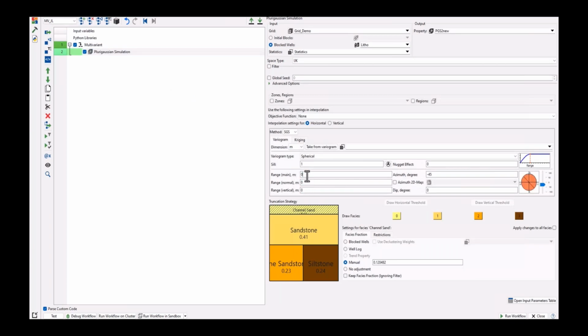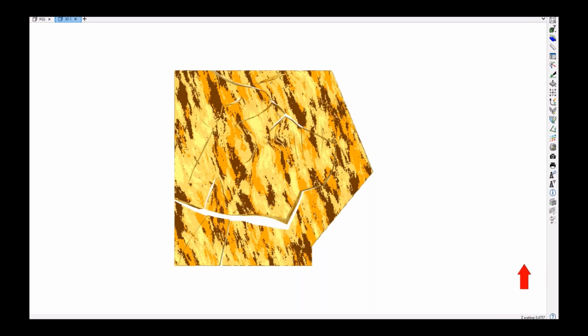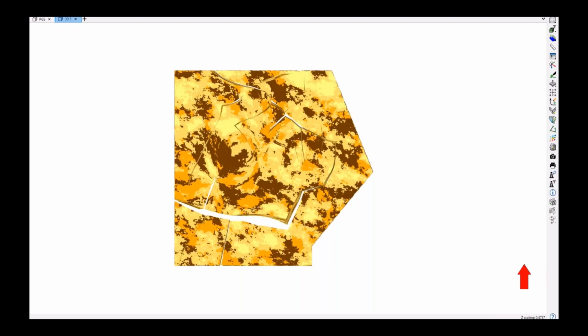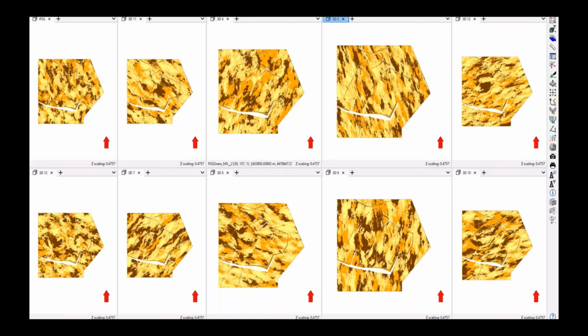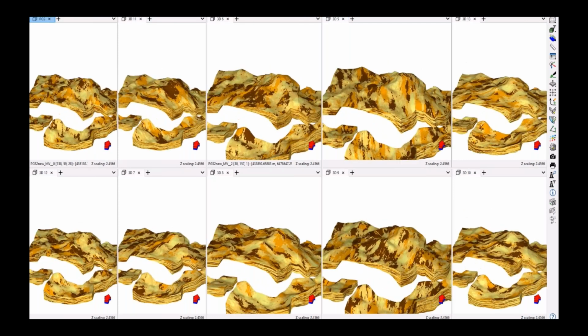What you want to do is anchor your calculation below your multivariant, and by doing this, it allows you to reference that local variables table that we created by right-clicking and adding our variables. We can see that each new iteration that we output within this multivariant outputs a new discrete facies model for us to analyze. We can view this in a multi-window display, looking at each of our displays, both in 2D and in 3D, and we can synchronize our cameras with ease.